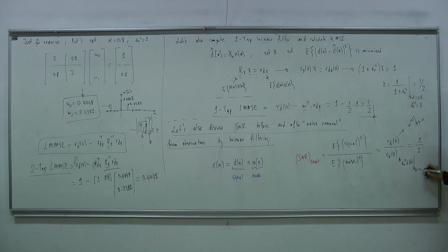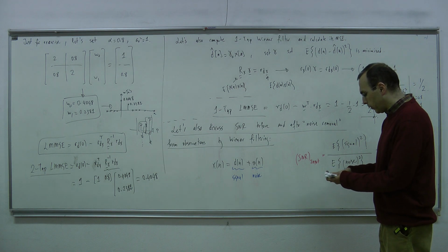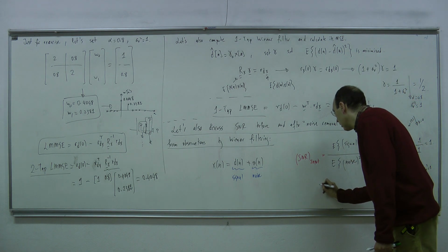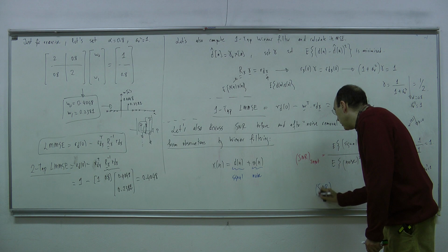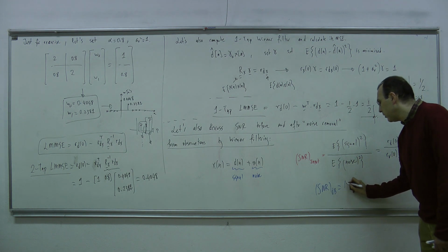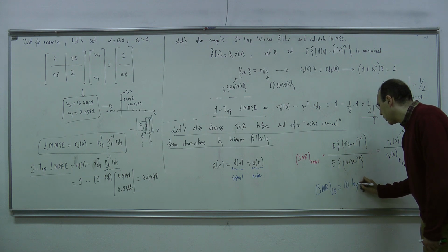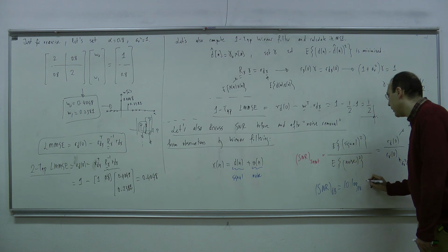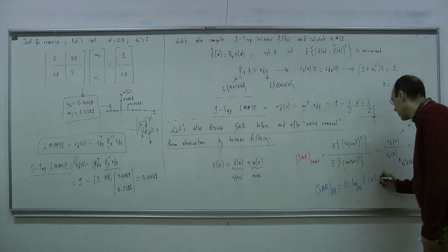That's also k equal to 0 and sigma_v squared equal to 1 in our numerical example. So we say that SNR is equal to 1: noise power is equal to the signal power. Let me also write the following. Sometimes we write SNR in dB. SNR in dB is as follows: you take the logarithm in base 10 of the SNR in linear scale.